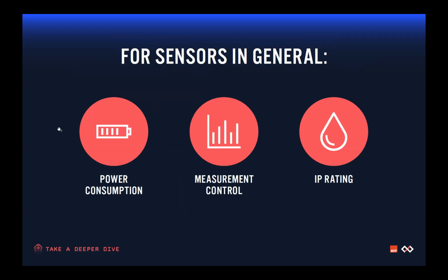Now, as long as we're talking about IoT sensors, there are also 3 really important other considerations that we would encourage you to think about. The first is power consumption, and we like to break that down into measurement as well as communication. Imagine that you're taking a whole bunch of distance measurements. You might not want to push every single one of those to the cloud because you're going to pay a pretty heavy power consumption price. You're going to pay for every measurement, and you're going to pay for every uplink or transmission to the cloud. Instead, you may want to take maybe 15 to 20 measurements and average those. And if the standard deviation is less than a certain amount, then you push that final chunk of data to the cloud. So think very carefully about power consumption, whether it's a distance sensor or any sensor for that matter.